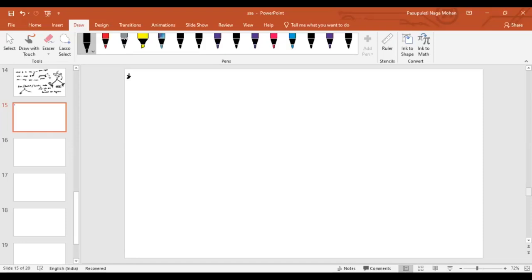The main mistake that people commit is that you will remember the formula, but you will forget the units. Let us say I ask you what is the Young's modulus of elasticity for concrete, what is the formula? The formula for Young's modulus of concrete is 5000 root FCK. Yes, sir. It is an empirical formula. In which unit do we have to substitute the FCK?